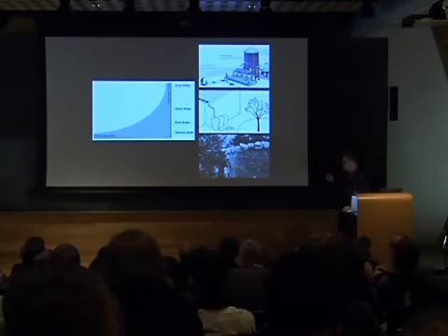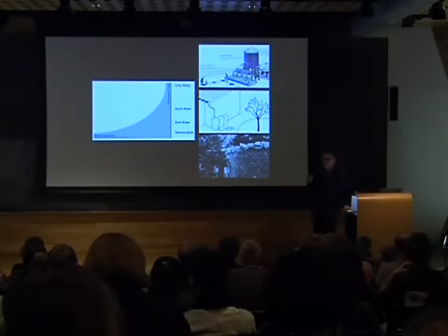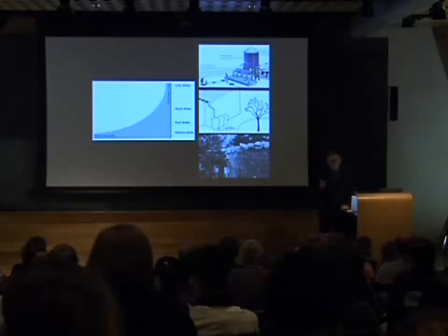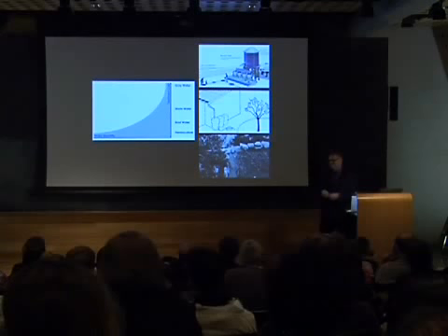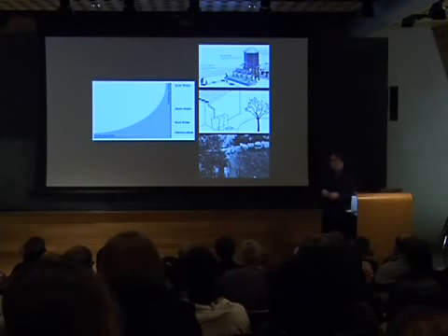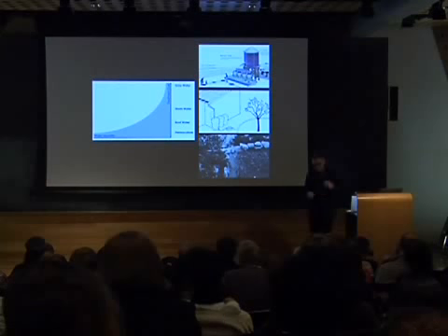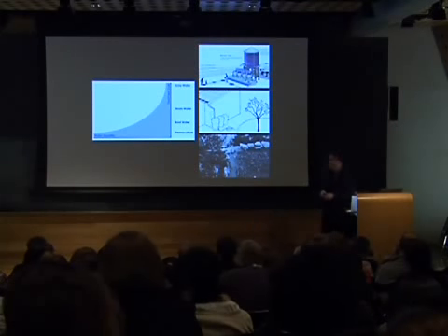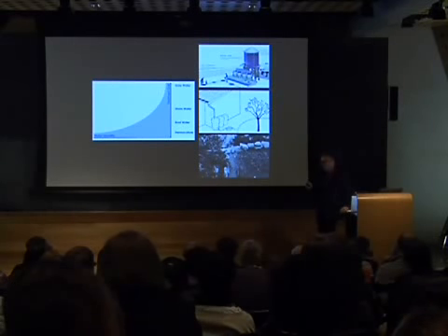When we started the project, the soil report came back and concluded that the soils had the porosity of asphalt on the site, which meant that all the water was leaving the site. And so we worked with Garn Wallace, who's a soil scientist in California, and we improved the soil, we perforated the soils, we worked to make the soils more porous to hold water, and we created catchments throughout the park. So the goal was to keep every bit of the 13 inches of rain that fell on the site.